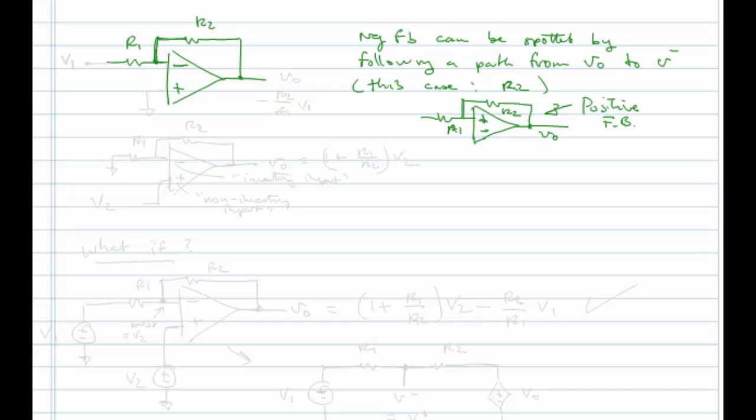So all the op-amp circuits that we'll be solving for the time being all use negative feedback. But you always want to check that. A tricky question would be if I gave you a circuit that actually looked very familiar, like one of these circuits we've already solved, but I wired it up such that it had positive feedback and asked you a question about it. You might just dive right in assuming it's negative feedback, but if you'd stop and say, okay, let's see, is there negative feedback? Well, no, there isn't. Therefore, for the inverting amplifier, it would not be minus R2 over R1 for the voltage gain, because that only applies when I have negative feedback.